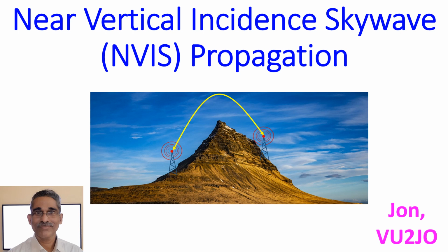Frequencies in the range of 2 to 8 MHz are suitable for bouncing off the F2 layer of the ionosphere. This would make communication better on 80 meter at night and 40 meter during daytime. During periods of low sunspot activity, 160 meter may be better.